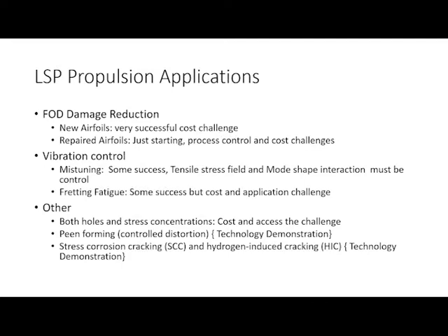That's where you've got a dovetail in a disc application and it's rubbing, and you go in and LSP the dovetail to prevent fretting fatigue. It's been successful, but again, cost and application challenges still exist.